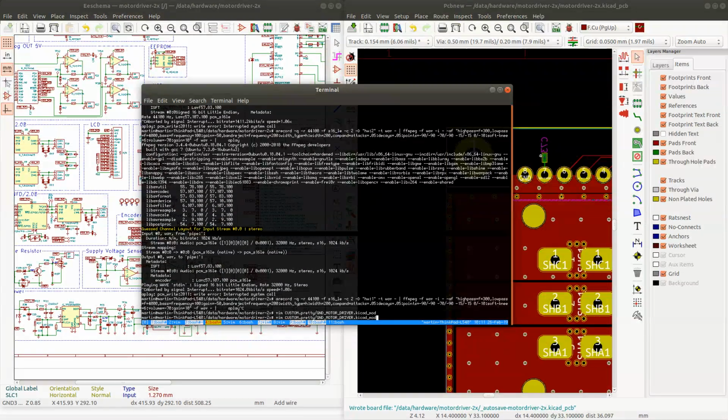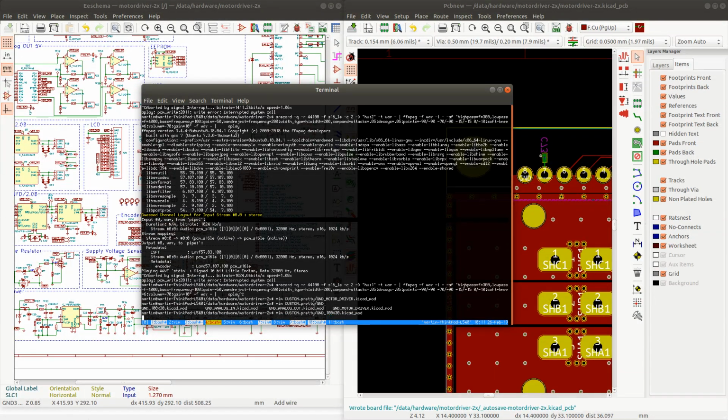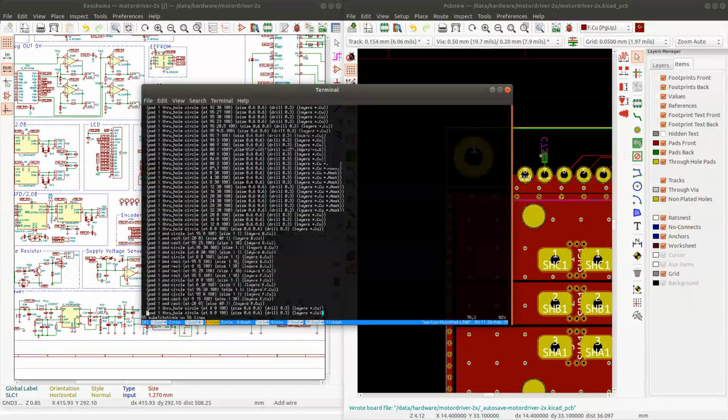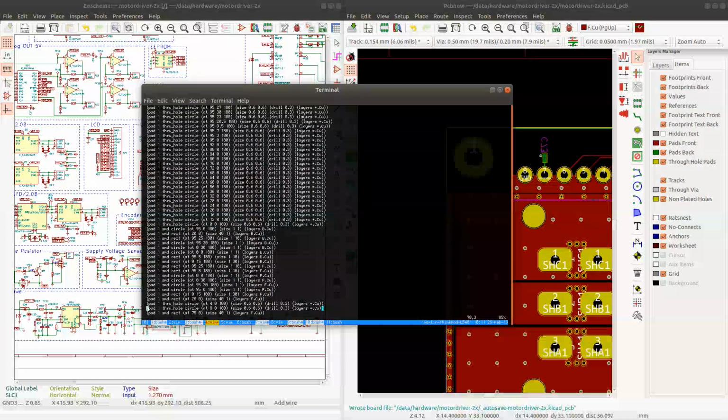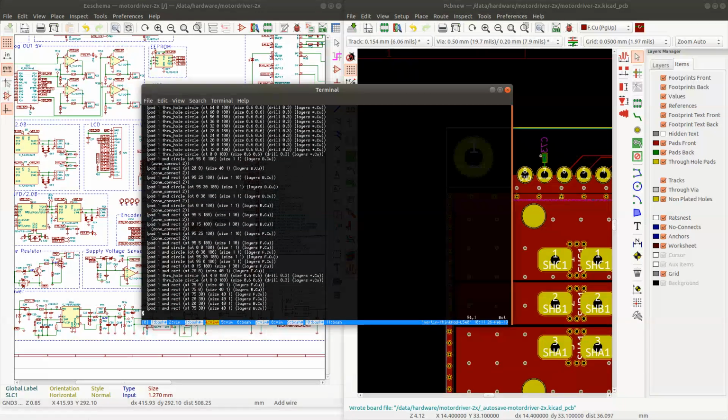Okay, let's go to GND 100. And remove that, and let's update the zone connect. This ensures that every element is connected using a solid connection to any pads that have the same, or to any copper areas that have the same net name.